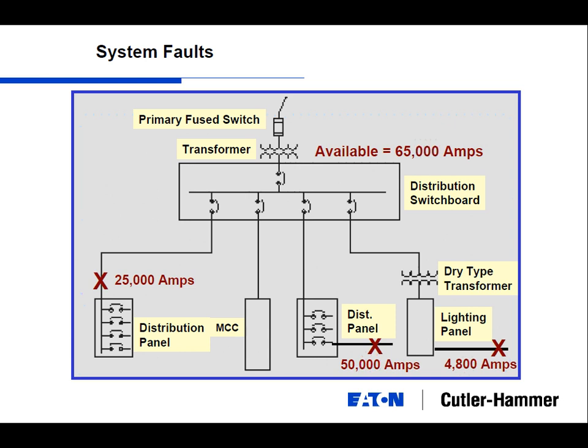So usually a dry type transformer that you'd see in a normal 30, 45, 75 kVA type is going to knock your short circuit down to something in this range. So if you ever have an application where you need to lower the fault current at a specific point, a good thing to consider is a dry type transformer, even if it's only a 480 to 480 volt dry type transformer.